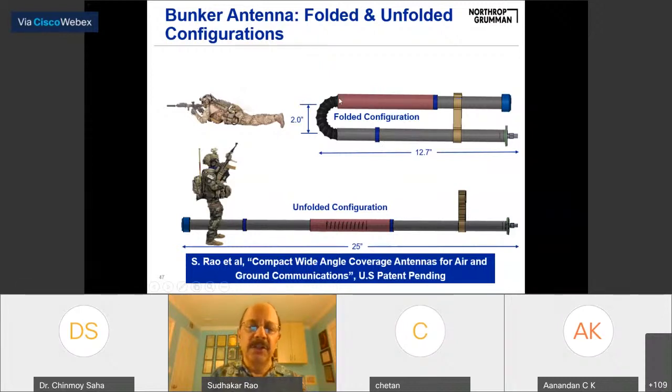Then the conduit, this is actually conduit, provides the flexibility. The region between the conduit and the handle is very important because we have to seal it against the atmosphere, so that water, snow, ice or dust cannot go in there. You have to be careful. The RF cable actually goes inside, and the connector is on the outside.